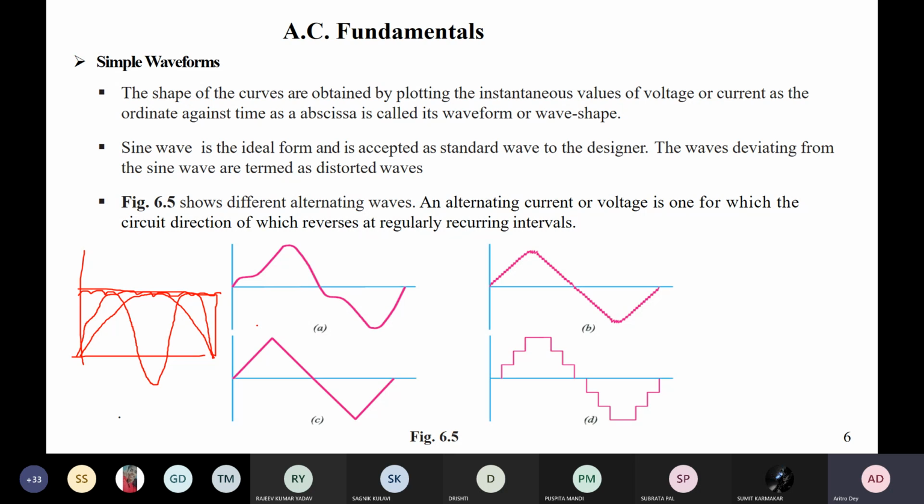So what is a nonlinear load? We may have many electronic devices which are operating at a high voltage. Those are called power electronics devices. Because of their presence, the fundamental will be distorted, because we are not directly getting it from the generating station; it will pass through transmission and distribution, and only then are we getting it. Because of the presence of some power electronic devices, we usually do not get a purely sinusoidal supply; there will always be some harmonics present.